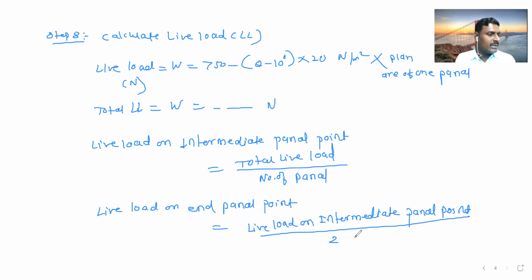So in this way we can calculate the live load also. So dead load and live load on each panel point we have calculated here. Similar to dead load, the same load will be transferred.